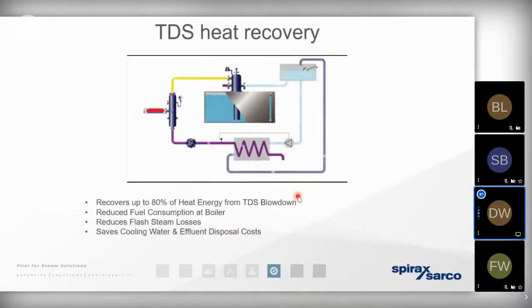We also mentioned last week that at the boiler house, we know that hot water does need to go to waste, but we also know that, as far as the TDS blowdown is concerned, because there isn't an excess of particulate present in it, it's in a good condition for being passed across a heat recovery solution. And of course, that means we've got another means of helping to keep the water in storage in the hot well at a nice high level.